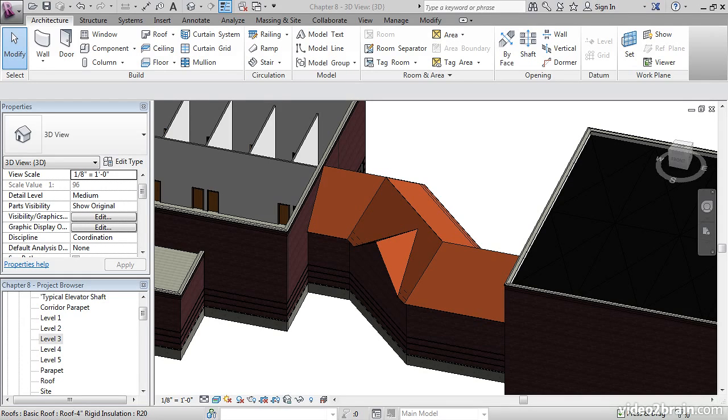The deal is we need to actually edit the footprint of the roof. Then we need to split the area of the roof that has become the dormer. We add a couple of slope barriers and we have a dormer. But actually, the first thing we're going to have to do to fix is the third floor plan and introduce a new topic called view range. As you can see, we have a dormer in here.